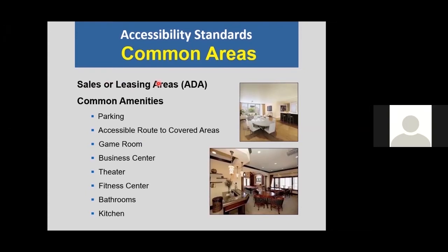the ADA standards. Spaces that are not typically intended for the general public, this might be our game room, our fitness center. Those, if they are intended only for use by guests and residents, they're not places of public accommodation. They would not be subject to the ADA standards in a private project, but they would be subject to being accessible still under the ANSI standard.